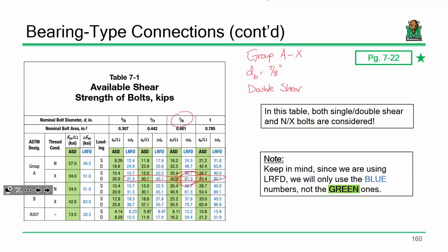That's a good question, and the answer is it's possible. I was doing some research on a bridge in Jackson County, West Virginia. It was near Ripley, and we were looking at this particular connection where there were these 2 through trusses, and then there were floor beams framing into the through trusses. So you had gusset plates and members, but then you also had a floor beam with an end connection plate. So if you looked at those bolts, yeah, they were in triple shear.